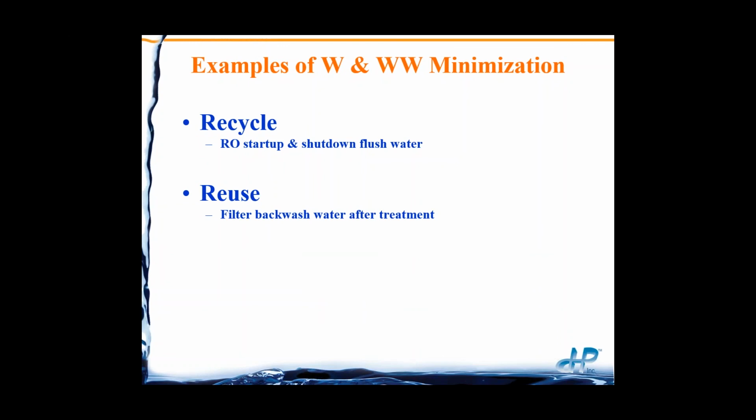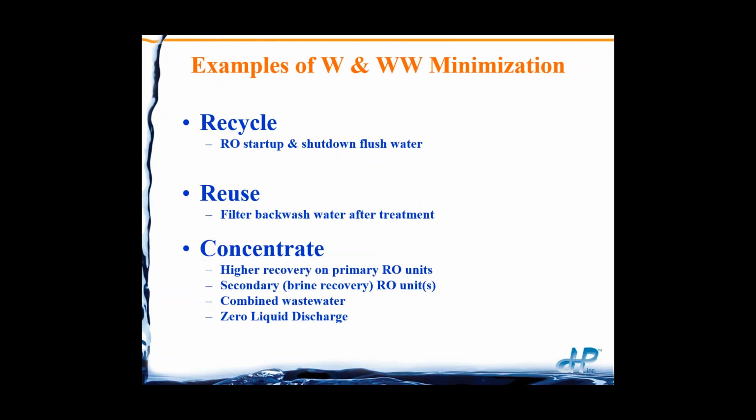So a reuse option, filter backwash, concentrating, which is wastewater minimization, but really they go hand in hand. If you reduce your wastewater out, you may also be reducing your water in, because if you're concentrating, like you're putting in either higher recovery RO units or you have a concentrate recovery RO unit, then you're making more permeate.